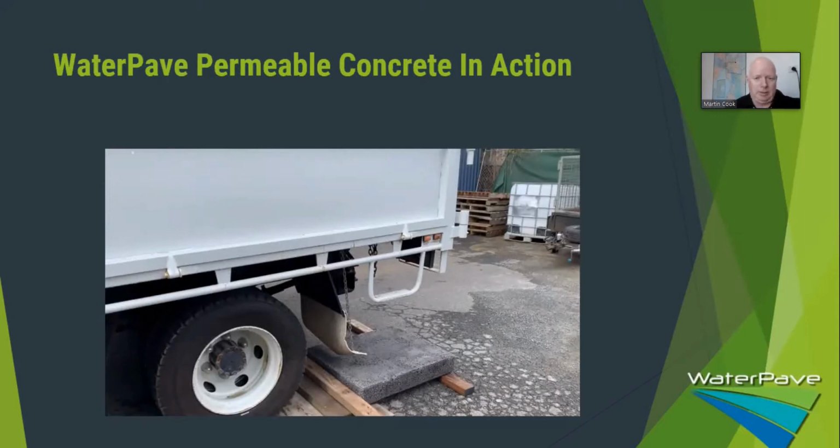These are just a few tests that we do for our permeable concrete. And this is quite outstanding performance when you can have a truck driving over a suspended permeable concrete slab with no reinforcement in it. That's something else I forgot to mention. Permeable concrete shouldn't have any reinforcement in it, like mesh or steel.